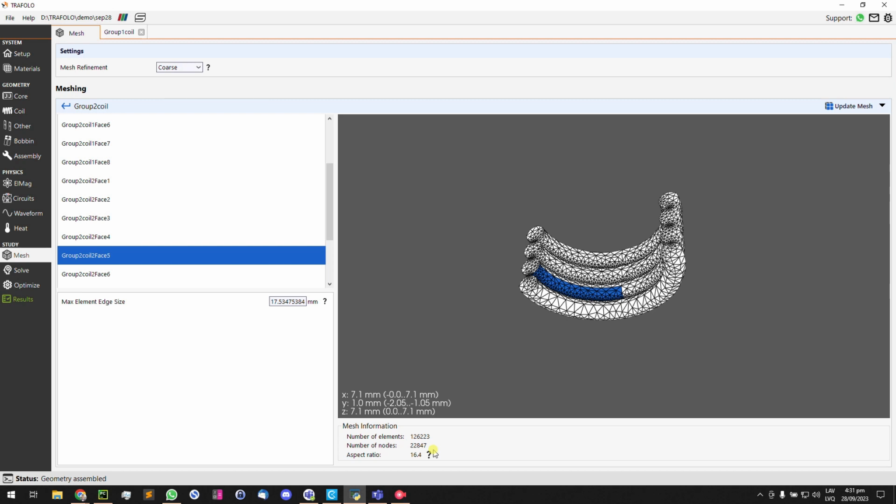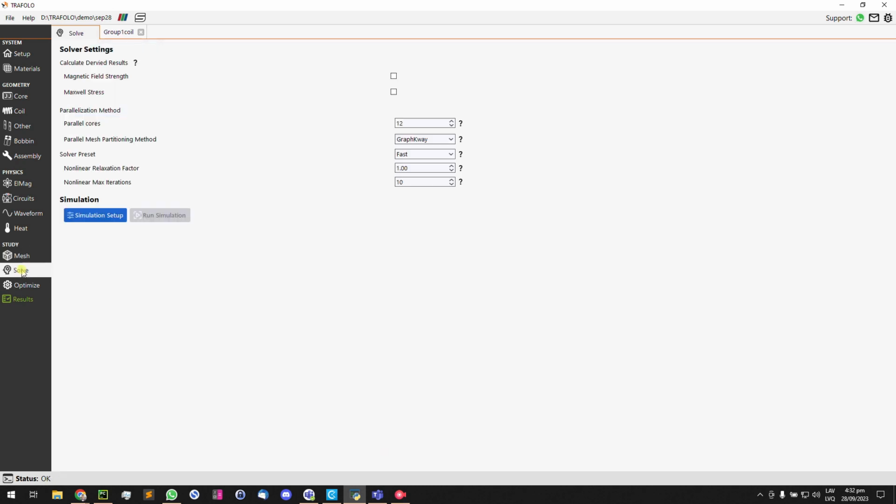So you don't want to refine everything with a fine mesh. No. You just refine those places that have the highest gradients, for example, highest magnetic flux gradient, highest current gradient, or whatever you want to resolve. So just put the exact number of elements in those specific places.